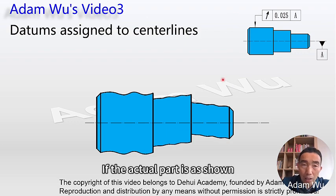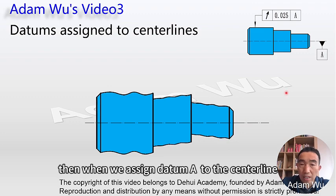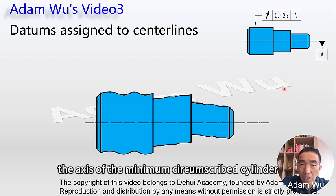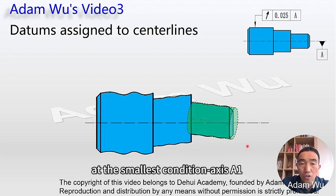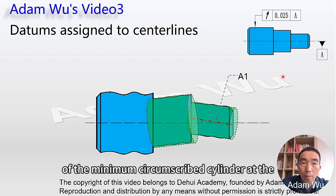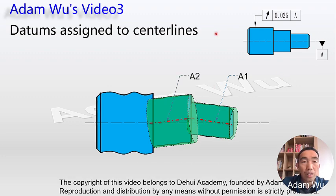If the actual part is as shown, then when we assign datum A to the center line, which axis does datum A refer to? It could be the axis of the minimum circumscribed cylinder at the smallest condition, axis A1, or it could be the axis of the minimum circumscribed cylinder at the intermediate condition, axis A2.